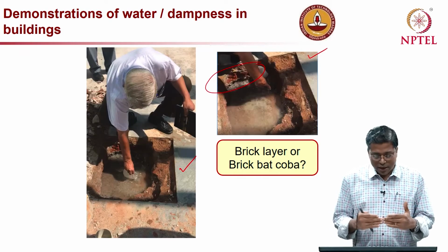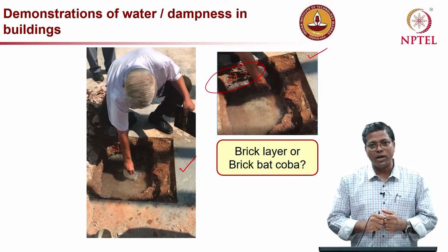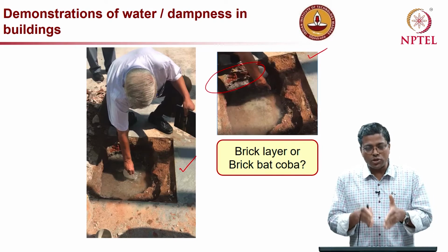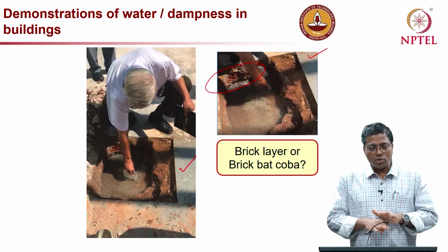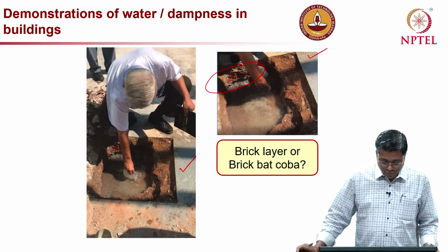Whenever you lay a tile, you should make sure that there is enough filler material, typically a 5 millimeter gap, in which you fill other material so that it seals properly, or a good pointing is possible.